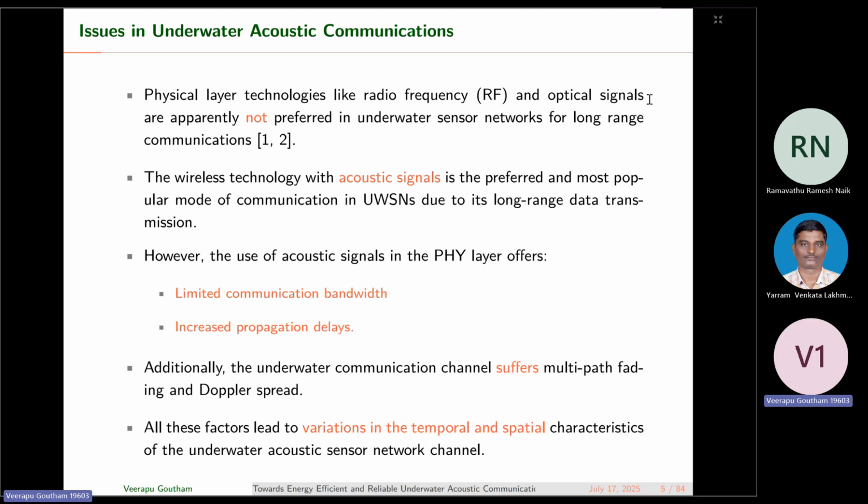Because the signals are traveling at 1500 meters per second, if you want to send the signals for longer distances, it will take more propagation delay. The main problems are limited bandwidth and increased propagation delays. These are coming because of the acoustic signals we are using in underwater.